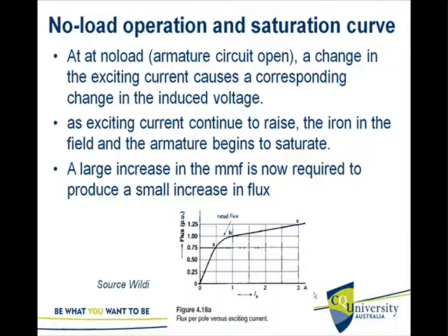Now let's look at no load operation and what is the saturation curve. The magnetic saturation we discussed earlier comes into the picture. At no load, the armature circuit is open, and a change in the exciting current causes a corresponding change in the induced voltage, which is fine.